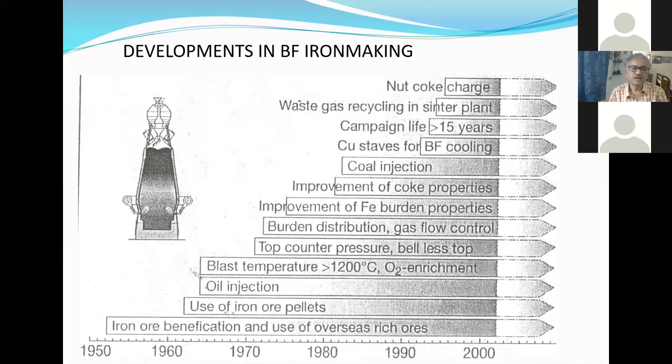Thermodynamically, I can show you that if you carry out 46% indirect reduction, which is the maximum possible, your thermodynamic efficiency or CO utilization becomes 84%. That means that is the maximum utilization that you can expect in the blast furnace. Beyond that, you cannot go. Some amount of CO has to leave the blast furnace, thermodynamically also. So your maximum CO utilization is 84%, and to do that, you have to attain 46% indirect reduction.